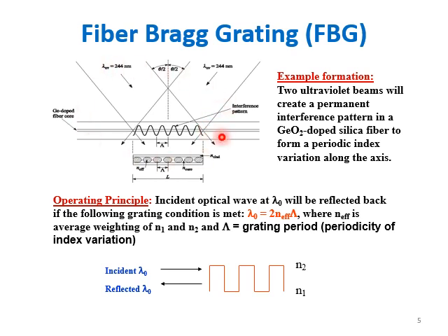This diagram indicates the formation of Bragg grating in a fiber core by means of two intersecting ultraviolet light beams. As you can see, the two ultraviolet beams, of different wavelength or the same wavelength, are passed from opposite directions at a certain angle. They come and hit the fiber core. This is the fiber, consisting of the fiber core over here, and light is going to be transmitted over here.